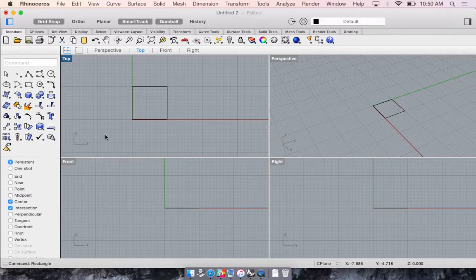How do you do it as a 10 by 10? I'm following the grid lines. 10 millimeters by 10 millimeters. How do you get it snapped to the center? Kind of like the cross between here to get it lined up. Oh, got it. So it should grid snap. Turn on grid snap. Okay. And then it should click down to the origin. Did that do it? Yes. Okay. So there's our 10 by 10.